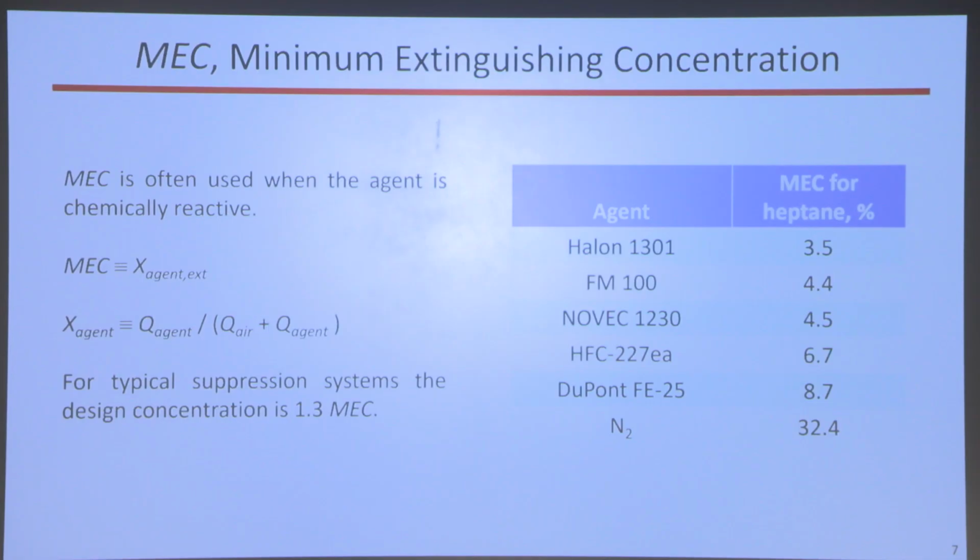So if you're protecting a data server room, usually it's a very fast response system. You'll have optical detectors to look for fire. And if it's detected, an alarm goes off. Usually you want to evacuate all personnel. And then a few seconds later, you totally flood the room with 30% higher than these numbers to suppress the flames.